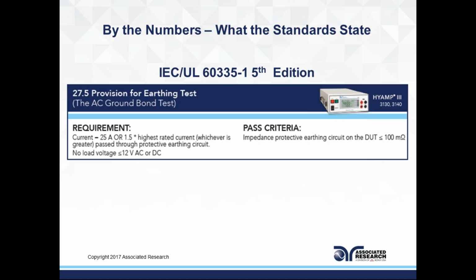Another standard here, 60335-1. This also requires you to have 25 amps, and a similar requirement of having less than 100 milliohms of resistance on your ground circuit.